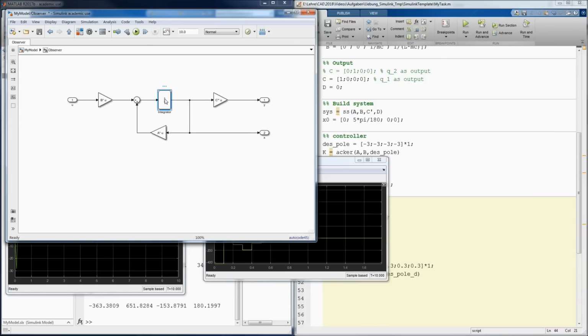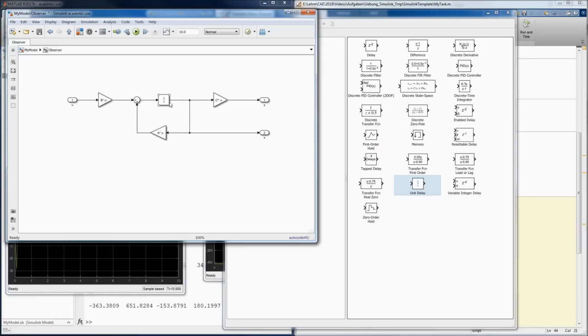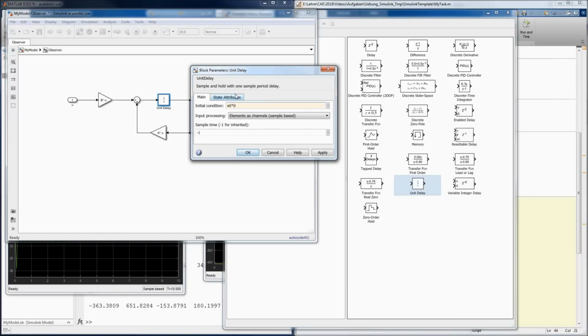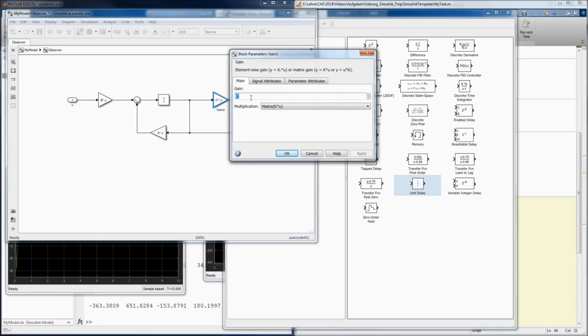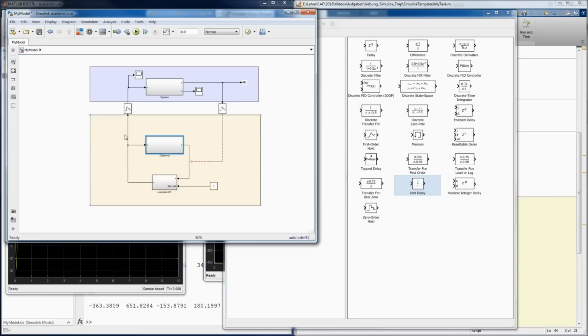What is inside it is, first of all, not an integrator. It's basically a time delay, which says that we are using a discrete time system. As the initial condition, we always have 0 because we don't actually know what the initial condition of the system is. You have here CD, AD, and BD. So right now we don't need to bring out the output of the system. We see that we are now reconstructing the input to state behavior of the system.